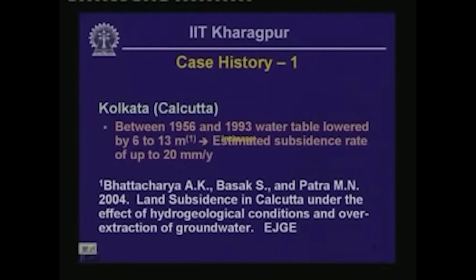Generally, the rate of subsidence, however, is much smaller, and it is generally lower than 13 millimeter per year. And since that rate is quite slow, structures that are constructed generally can cope with that slow rate of subsidence, and the serviceability of these structures, buildings or other facilities at these areas, is not compromised to a significant extent.